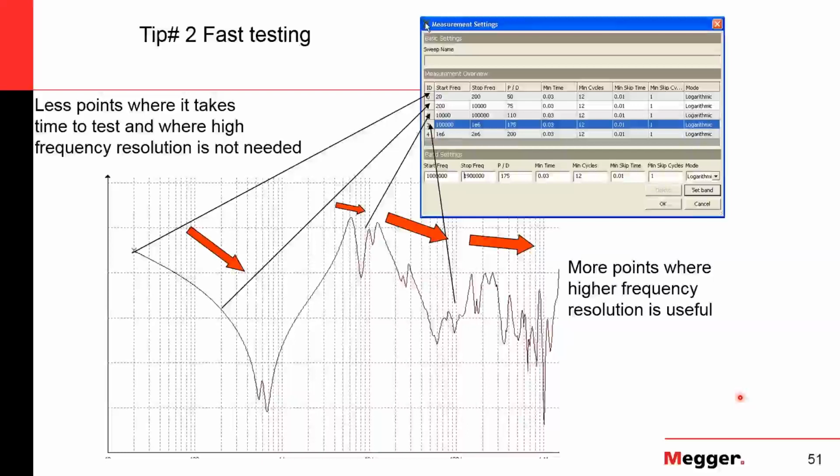So lead placement. Just looking in the software, what's nice is it indicates to you where to connect everything. As I said, once again, the SFRA, the FRAX here, it only does one thing: outputs a voltage at multiple frequencies and measures the response. Your job is to make sure you're connecting it up. So what you do is you look at what we say and you say, okay, the first